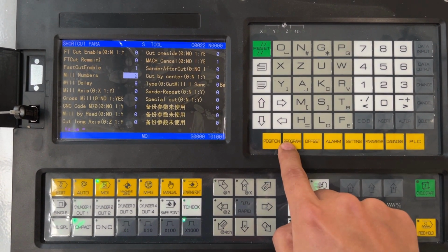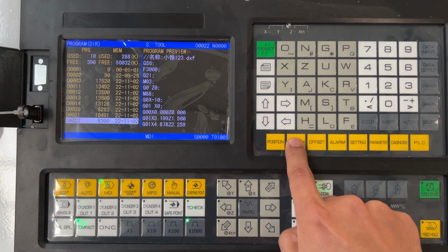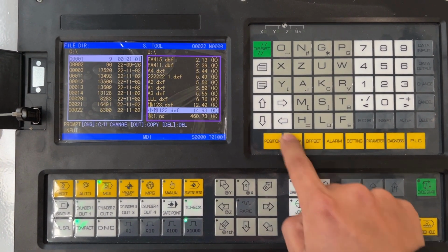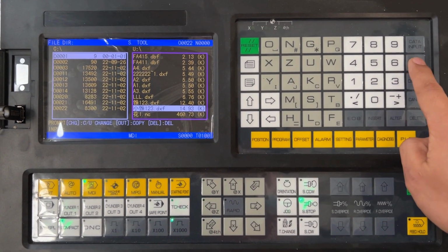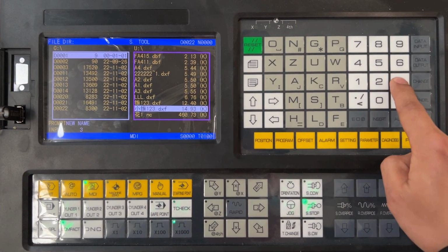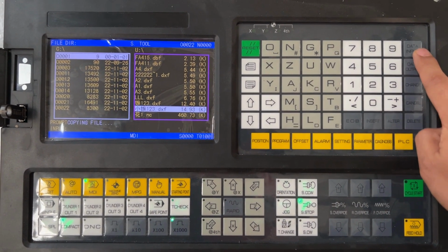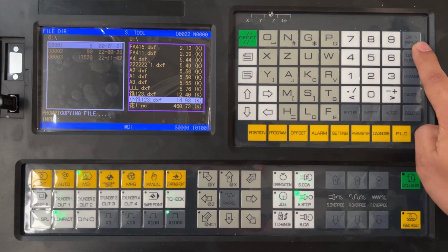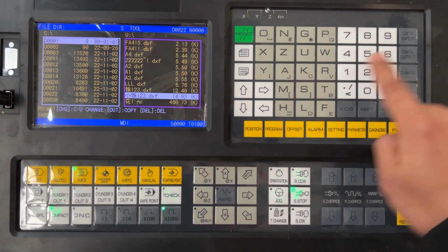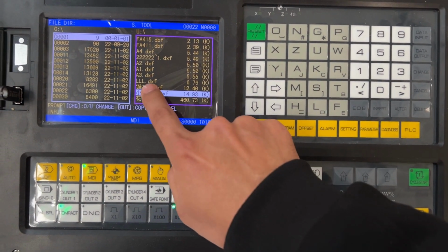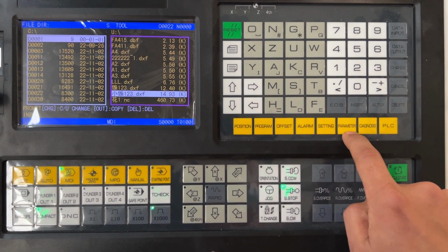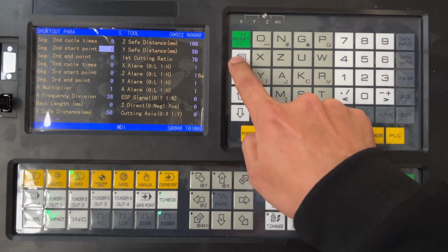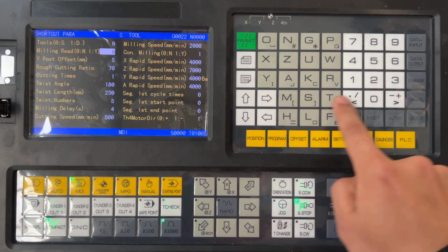According to the sequence of operations, import the turning DXF file into the machine. The new name is 30. Spindle or grinding wheel work needs the names set as 31 and 32. After the turning program is imported, continue to set parameters and import the program of the spindle, the milling groove.